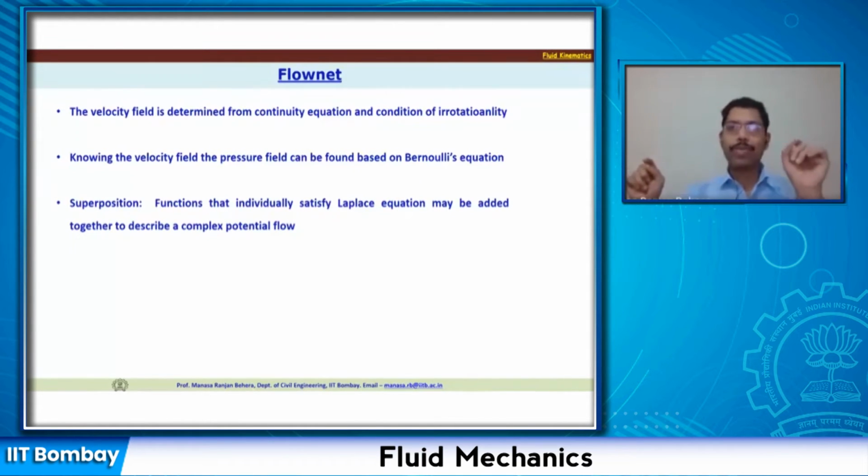So if I know the pressure and velocity at one point, and the velocity at the other point, I can find the pressure at that point. Vice versa, if we know the velocity field all through, then it's easier to derive the pressure field. So from the psi function and phi function, we can find the velocity fields, and we can derive the pressure field based on that.